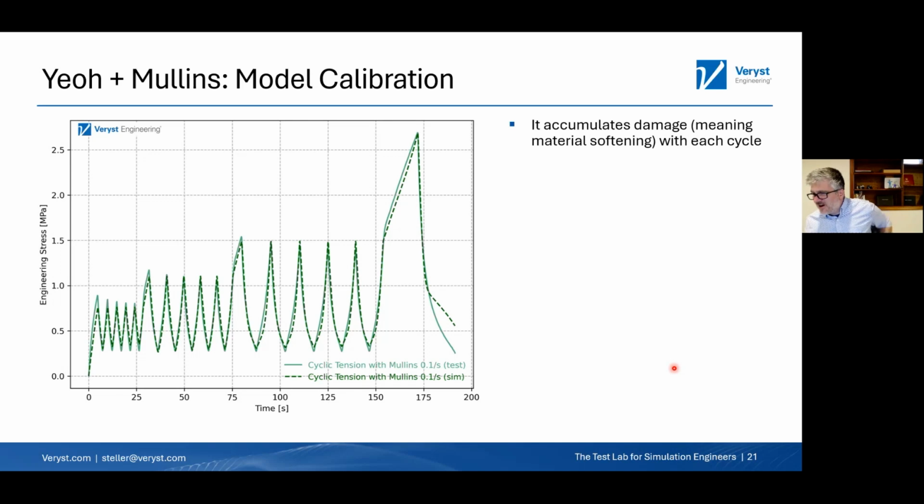Our applications are all biaxial stress. Can you get reliable viscoelastic, hyperelastic, viscoplastic models from uniaxial testing? The answer is going to be it depends. If you're talking about rubber materials generally, the finite element code manuals, including ANSYS, will tell you to test in tension, biaxial tension, and planar tension or shear. Depending on the model you choose, that can be right.